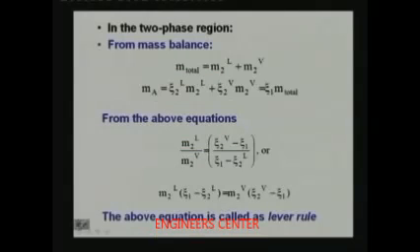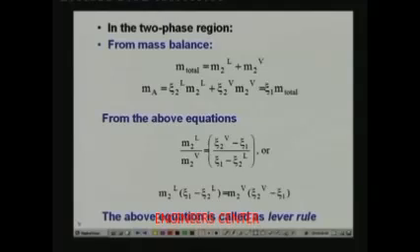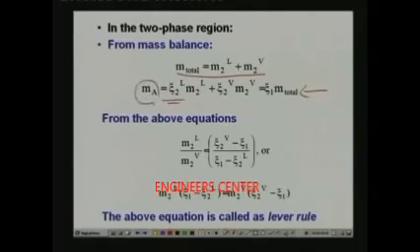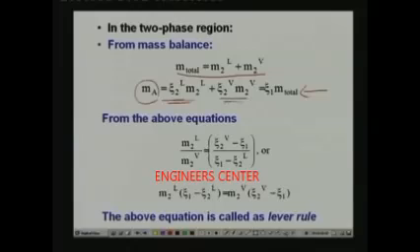And for the two phase region, as I just explained, you can write the mass balance. The total mass is always conserved; total mass is nothing but M2L plus M2V. You can also write a conservation equation for the ammonia mass. This is nothing but the total mass of ammonia in the mixture, that is, ammonia in the liquid phase plus ammonia in the vapor phase.